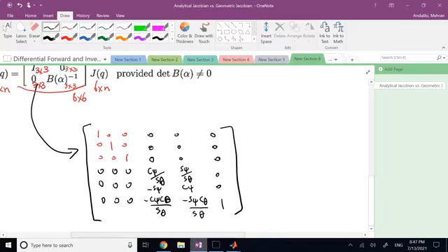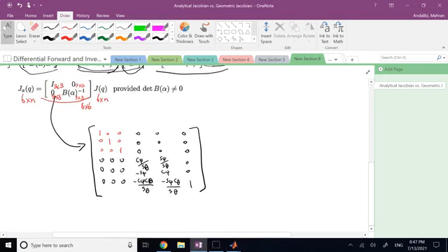Yes. So this is going to be that matrix that you have to multiply by whatever Jacobian we had from the previous cases. Let's say, for example, with the SCARA, or with the 6 DOF. Of course, for the SCARA, you only have one angle. You have no problem.